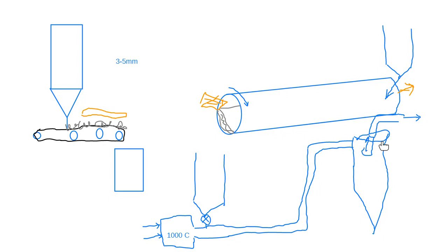So it first has to go around, so it'll maybe do 20 revolutions by the time one of the gas molecules gets to here, where it can actually go up the tube. So that's why this tube extends a little bit into the cyclone.